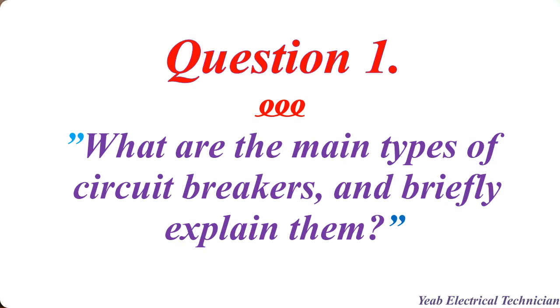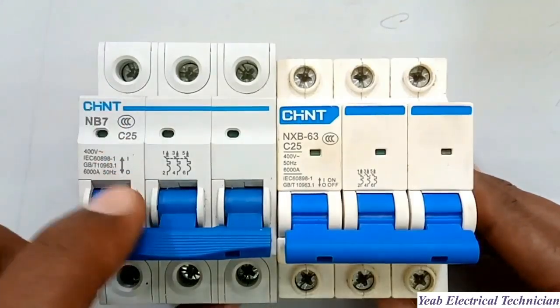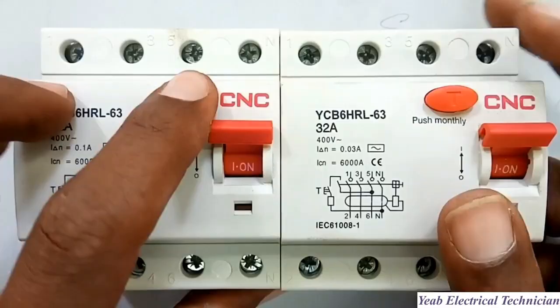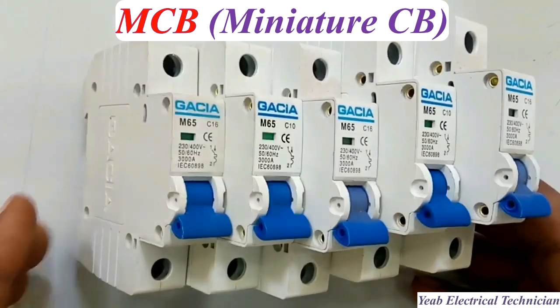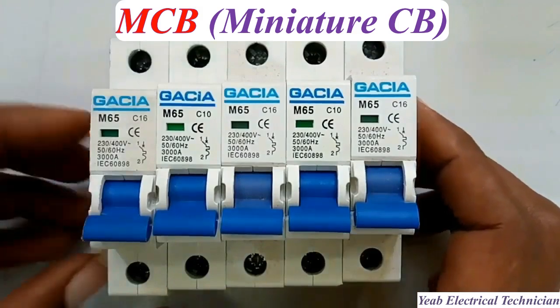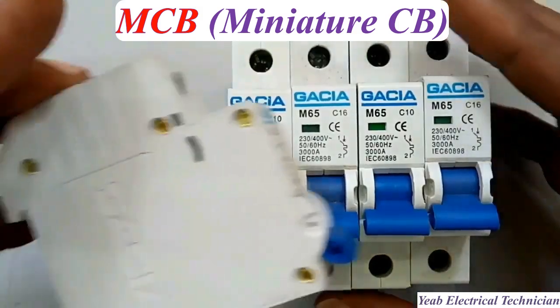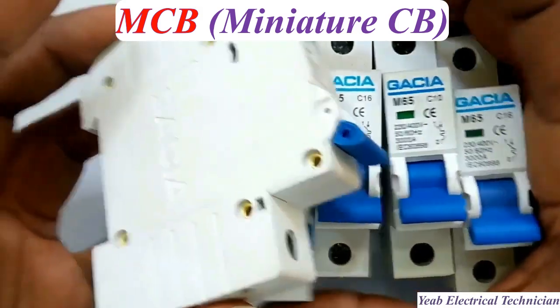The first question, what are the main types of circuit breakers and briefly explain them? Circuit breakers protect electrical systems by interrupting current flow during faults. Common types include MCB, which is a miniature circuit breaker, an automatically operated electrical switch that protects a circuit from damage caused by overcurrents like an overload or a short circuit.